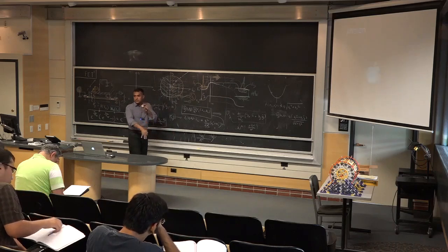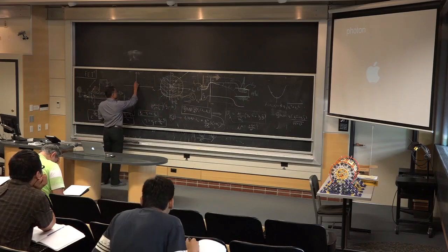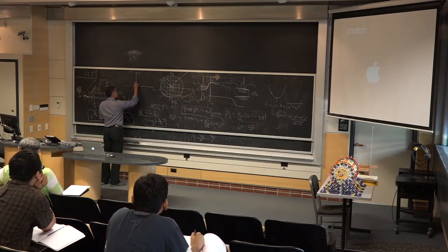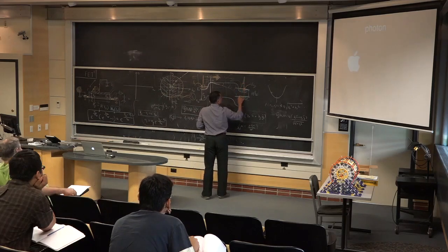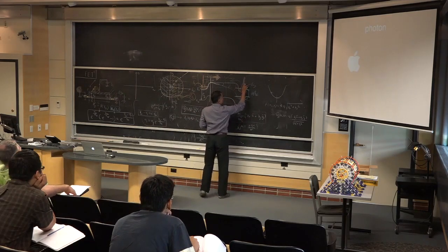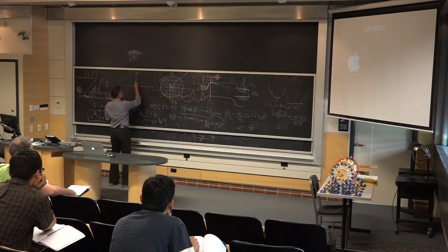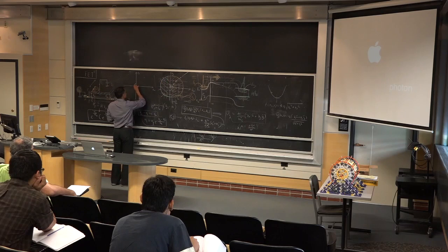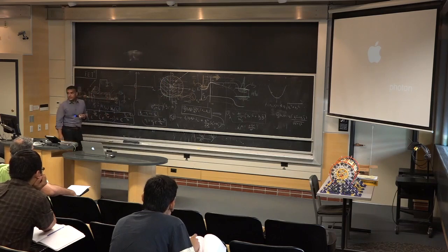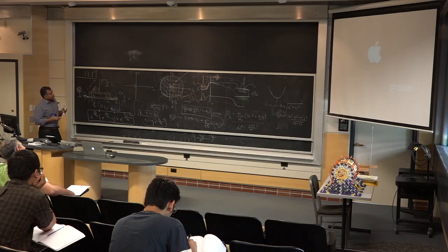It's gone down exponentially because the barrier height has increased. It's still injecting some, because there's always a tail. It's a much smaller tail, but there is a tail. So maybe this whole big circle going to the left has suddenly shrunk to a very small circle here. That's the one that's injected to the drain.